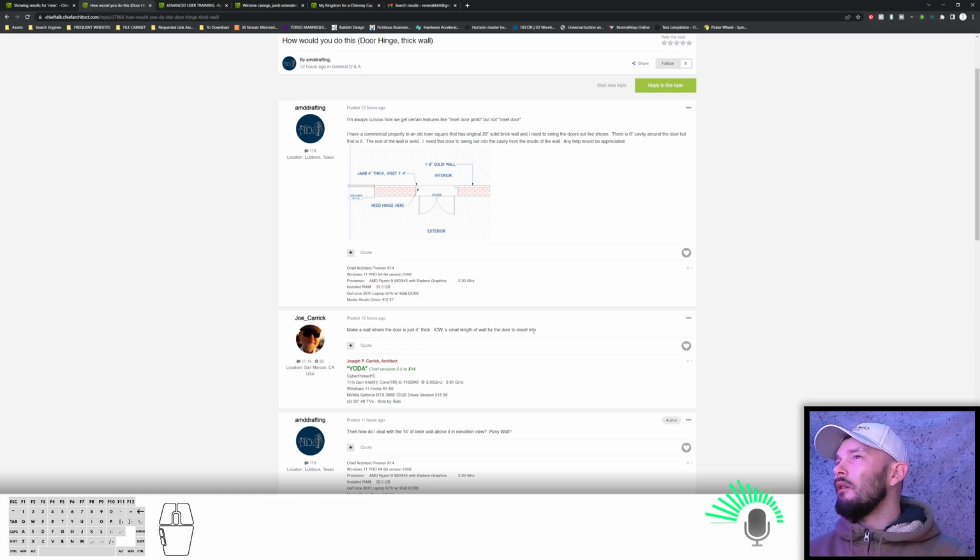You can do a double wall. That's a way to do it. You can do some symbol hacking. That's a way to do it. I prefer the double wall. It's very predictable, and you're going to have your door set to frame through. So that's just a really easy way of doing it, and being able to control recesses on top of that.